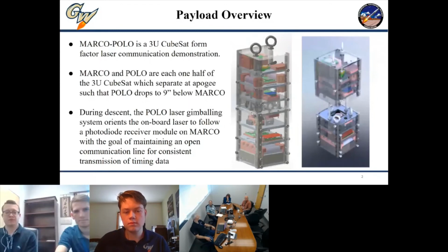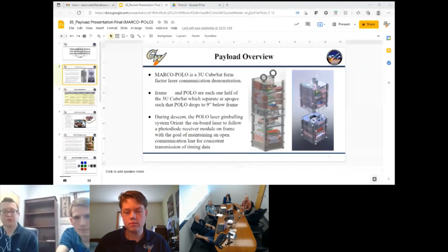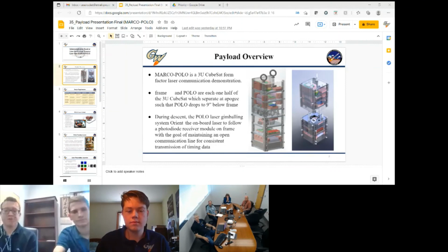But they do fully separate to where there's no mechanical engagement other than just the tether? Correct. Yes. Probably a strain factor in the cable for pushing them apart. Yeah, it's just standard aircraft cabling there. Very rigid. The cables themselves, I think, are 9 inches, but now that I'm thinking again, the eye bolts extend that a little bit, so it's more along the line of 10 inches.